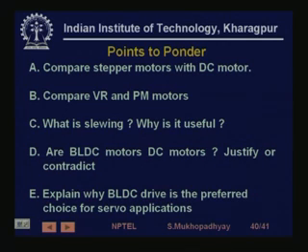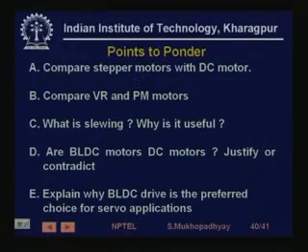Are BLDC motors DC motors? By construction they are not, but by operation they are made to behave, and by behavior they are like DC motors. So you can either justify or contradict, and explain why BLDC drive is the preferred choice for servo applications, because you can have performance like a DC motor without the problem of the commutator and the brush. You can get very good torque because you get very good magnets.